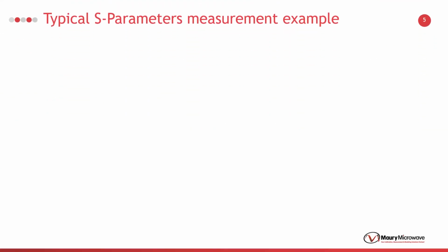To understand the need for uncertainties in S parameter measurements, let us imagine the following situation. Let's assume that an engineer has to design a power amplifier, PA, with at least 12 dB gain, or S21, over the frequency band from 10 GHz to 42 GHz.